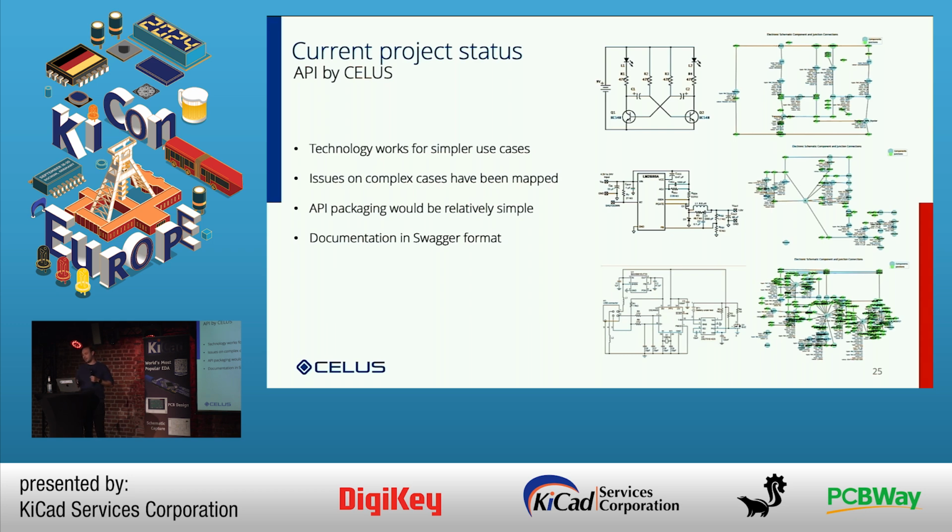So if we're thinking about how to deal with the data that was created on KiCAD, I think it does also need visual verification, just like you would do with a simulation, for instance. You simulate and then you verify that the results are what you're expecting. Here, the same thing: you generate that, and you verify if that is what you were expecting. And if not all the information is available on a schematic, you may need to add it later on. So one example here, I may load resistors on my schematic, but if the image does not contain any information on the footprint, then I will have to add that manually.